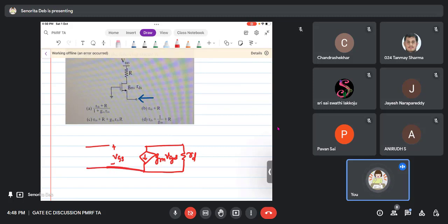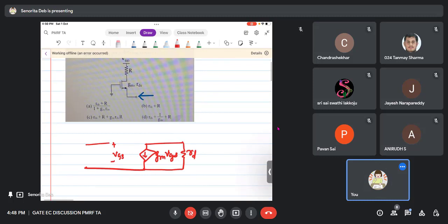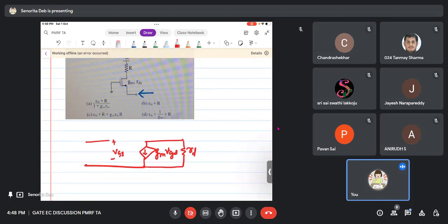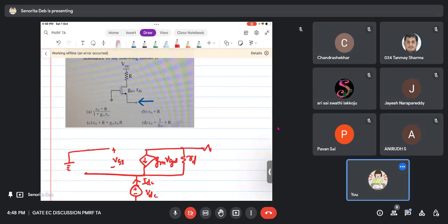Okay, small signal model. This is not grounded, right? This is not grounded. What is grounded is this one. This is ground, and you have to find it from here. So I will apply a plus minus VDC at this point, because I have to find the output resistance at that point. And you see there is this R here, capital R, to VDD, and in small signal all the DC sources are 0. So this is ground.